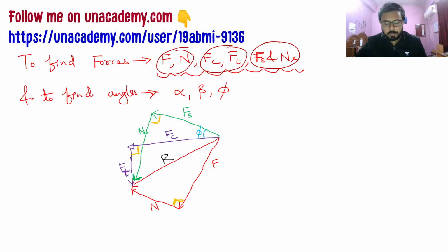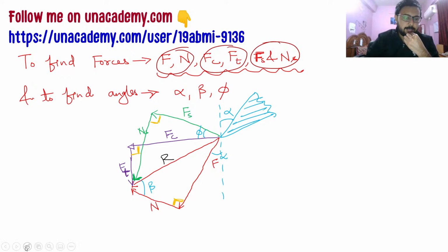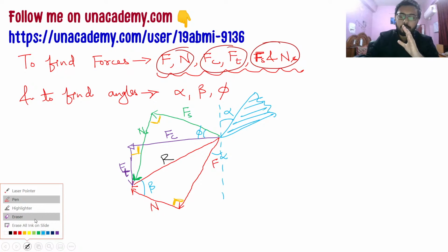Let's draw the angles now. This angle is phi, which is the shear angle. This angle is beta, the frictional angle. And here we have the single point cutting tool, and this tool's face makes the angle alpha with the reference plane, which is vertical. That is the rake angle, and you must know this because we have discussed it. So this whole geometry you have to completely remember.